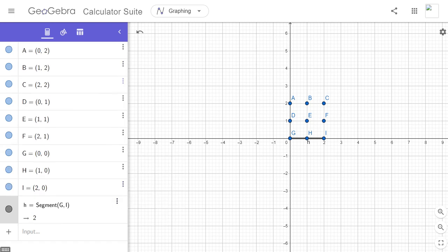What I want to do is name them something. So rather than let the computer take over, I want to name them. Here I'm going to use lowercase l and the underscore. I don't know if you can see that, but that's created a subscript, L1 equals, and then I can call that segment AC. Now I have L1 and then L underscore 2, and I'm hitting the right arrow. Do you see the cursor's down in the subscript location, where if I were to type, I'd have more subscript, but when I hit the right arrow, it hops back up, and I can do equals segment DF,